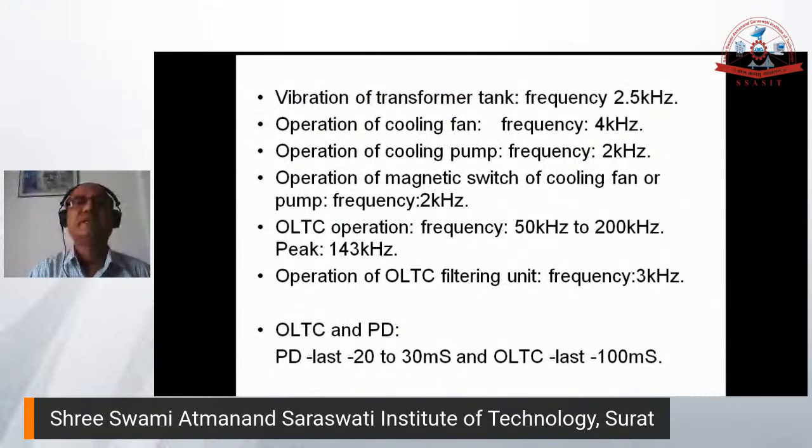Vibration of the tank is also going to create a noise, that is 2.5 kilohertz. Operating a cooling fan also creates acoustic or mechanical noise, that is 4 kilohertz. Then the cooling pump, which is circulating the oil, also creates pressure pulses, that is 2 kilohertz. So they have different frequencies. Cooling fan is 2 kilohertz. OLTC operation is going to give 143 kilohertz.